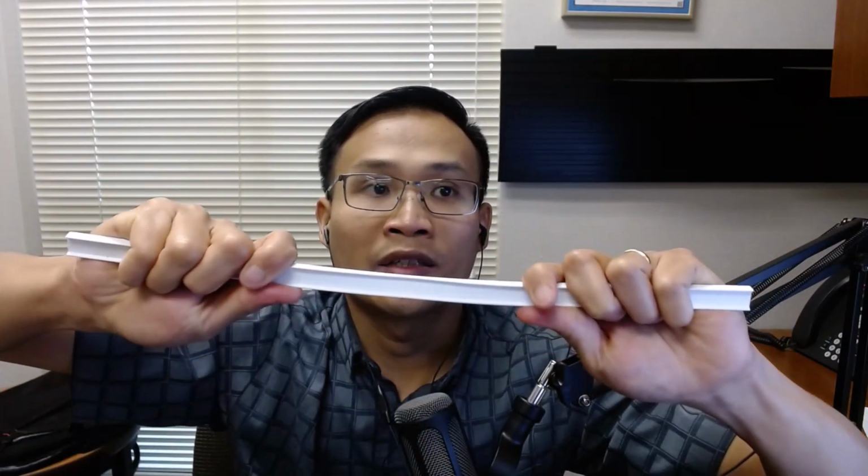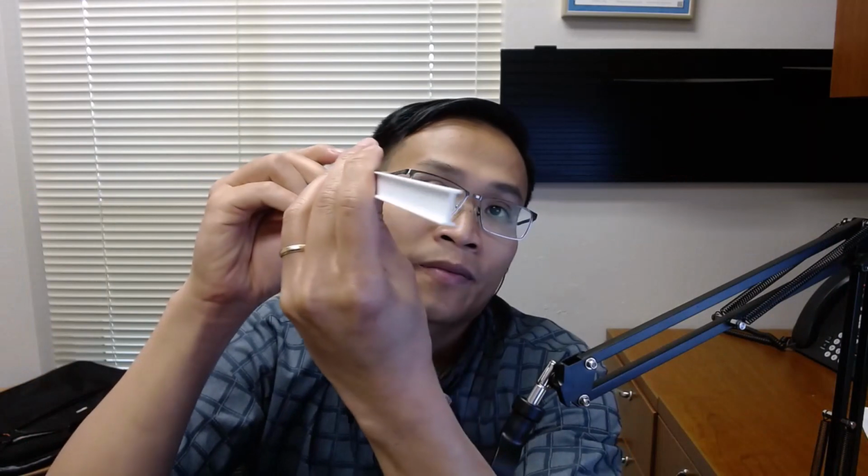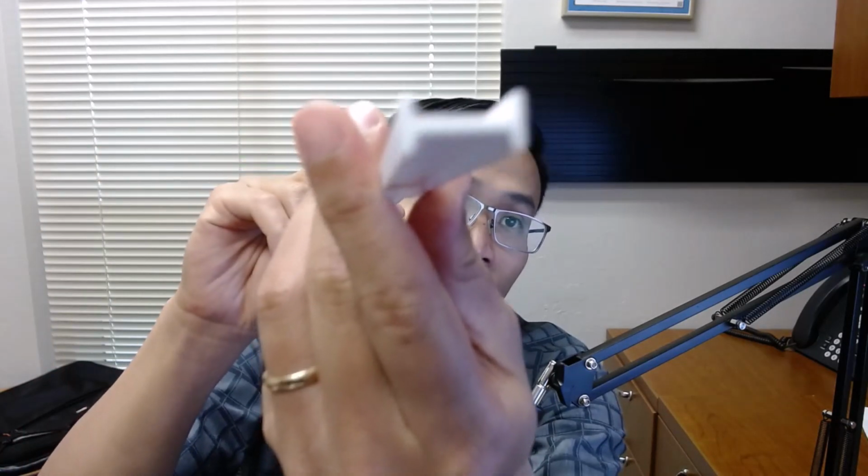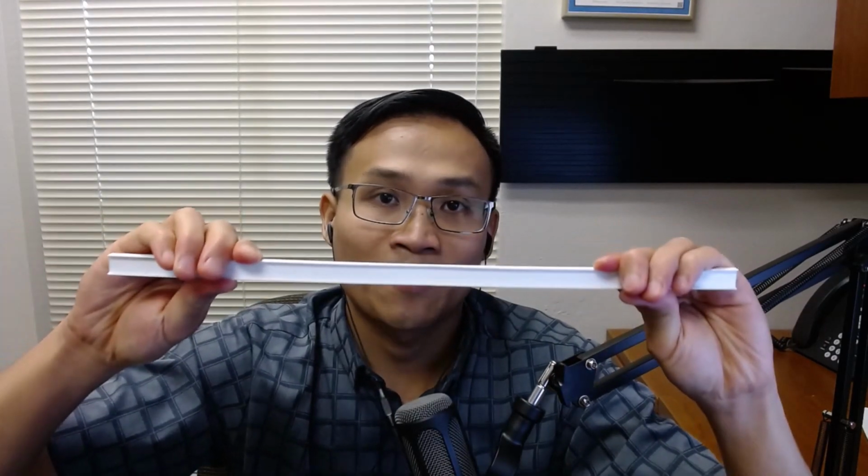You see that if I keep it like the letter I, it's very hard to bend. However, if I rotate it over here, it's not an I anymore. It's an X. And if I bend that, it's very easy to bend. So if I bend around the I, it will be the x-axis. If I bend around the X, it will be the y-axis. Because we want to maximize the capacity of the material, we should bend around the I. That's why people call it an I-beam, they don't call it an X-beam.